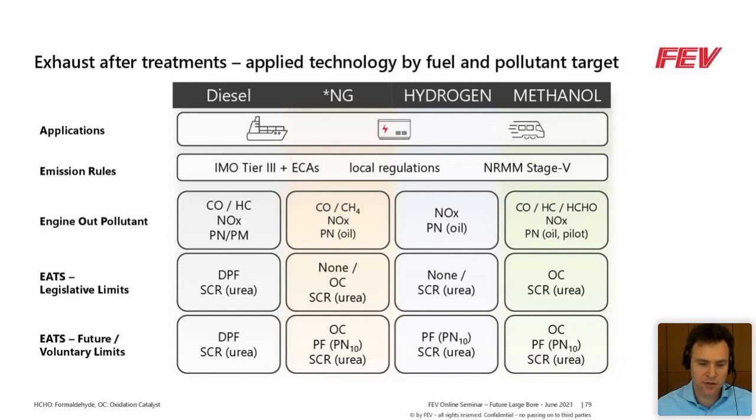So all these complex different combustion systems will at the end trigger different kinds of exhaust aftertreatment systems. But a common approach that also simplifies our life is that the urea-based SCR will work more or less for all the combustion system applications when we have to discuss NOx reduction.